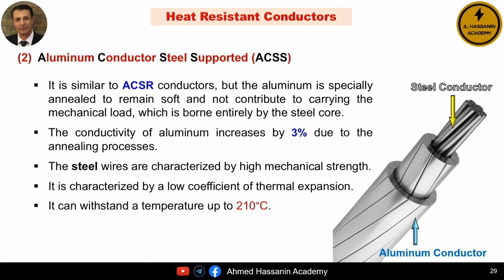Among the most important advantages of this conductor are high mechanical strength due to the steel wire core, and a low coefficient of thermal expansion, which means that the conductor does not expand significantly in summer or at high temperatures, nor shrink excessively in winter or at low temperatures.